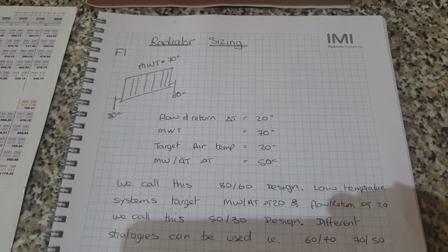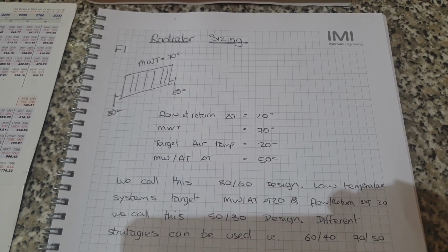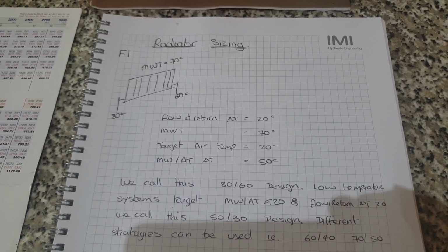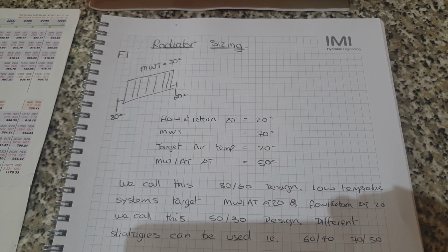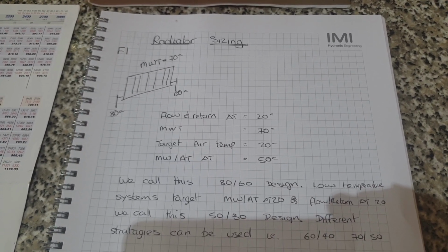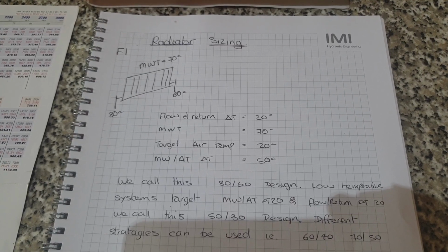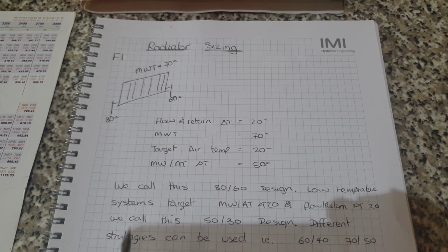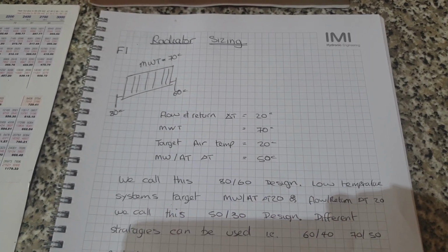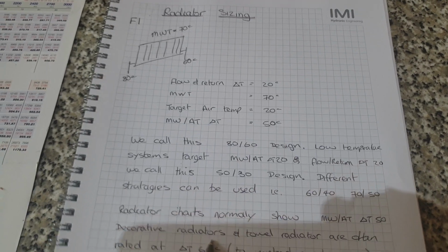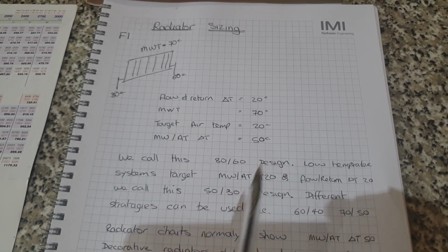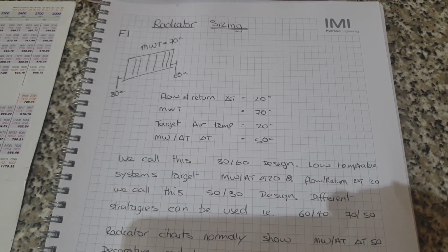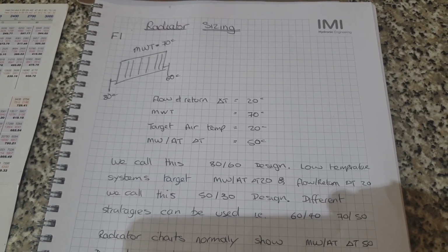But all the same, we should understand it, and we should understand how we calculate our F1 factor. Now you might want to retro calculate that F1 factor as well. You might want to look at the size of the radiators you've actually got and look at the heat loss characteristics of the building, and from that you could work out what the original design strategy was, and it may not have been delta T50, but that's a little bit more complicated. But here today we're going to just cover how to calculate the conversion factor for your radiator, so you select the correct radiator according to your design criteria.